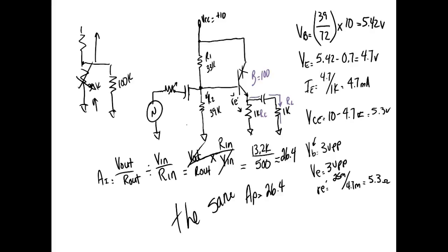So this guy is setting that voltage right there. Instead of that 39K setting it, now we have a 1K setting it. It's the predominant resistor, so we should expect it to go down. Transistor, of course, is going to be cut off, right? You understand that. So we should expect VB to go down. If VB goes down, this is going to go down. We could probably calculate it. It's going to be really close.